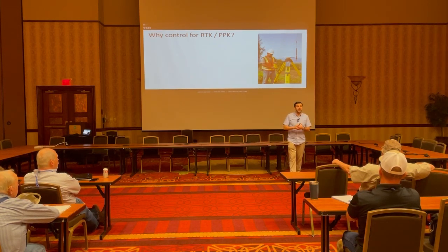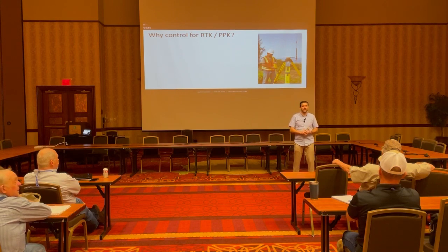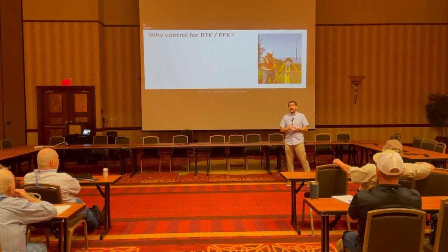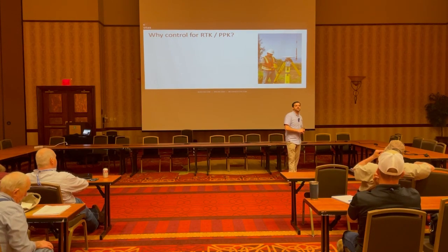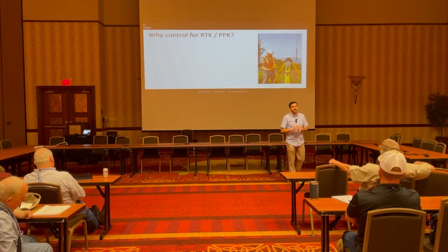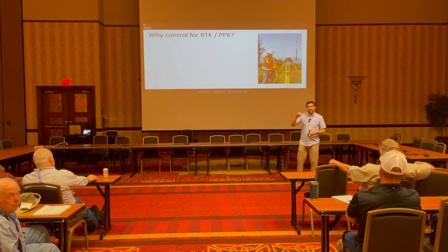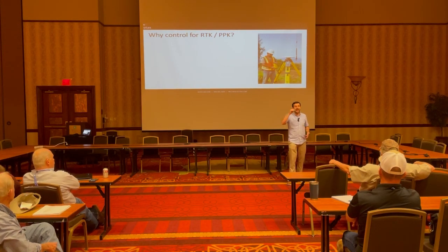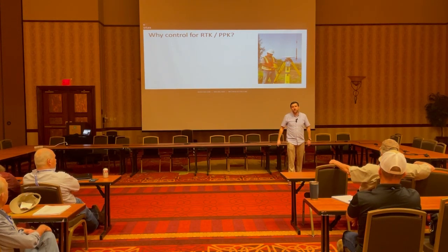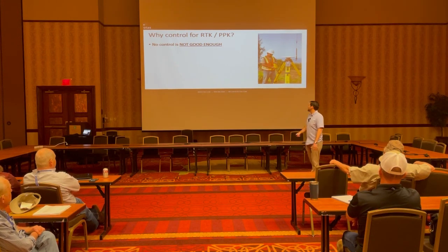However, we think that is an irresponsible thing as a land surveyor, both because you might submit bad data and might not have any way to know it, and because it's often super complicated and expensive to validate with that level of precision and reliability that you got it right. So we think that no control is not good enough for a surveyor.